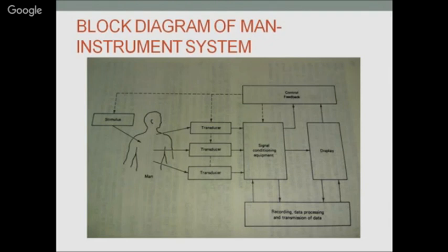So first thing, you have to design a very good amplifier. And the amplifier you use will not be a single-ended input amplifier. A single-ended input amplifier will not work here. As in the case of EMG, I discussed that you are using 2 electrodes. So differential amplifiers are mostly used in the signal conditioning circuit of biomedical measurement systems.